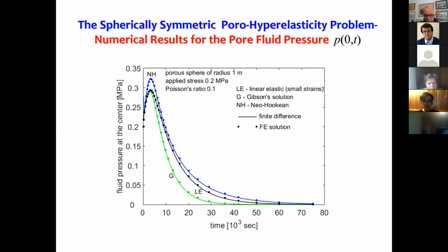They have put pressure transducers inside the sphere and then compressed it, and you get the pressures rising up. Nowadays, you can get transducers where there are no leads. You just put the transducer in the middle, and it can transmit the pore fluid pressures to the exterior. So there's absolutely no possibility of leakage occurring from the center to the exterior. So yes, you can see that the pressures do go up, and then the pressures reduce to zero as time progresses.